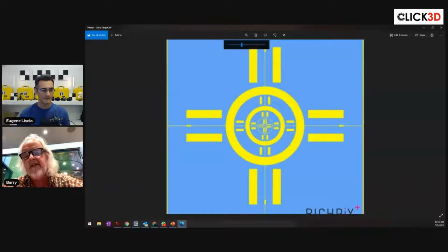So that's really what it is. You use the different paired lines further away. So if I'm less than about 5 meters away, I'm going down to, in US money, the paired lines at the bottom middle are only about 0.02 of an inch separation, and going out further and further. I just find that this gives me a consistent measurement, and also then if I need to pick that control point in my photogrammetry software, it gives me more than a fighting chance.